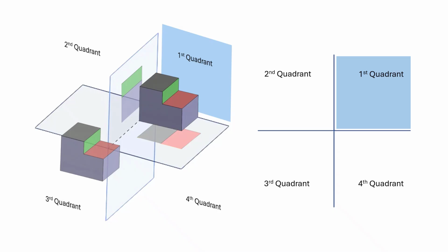Now, if we talk about third angle projection, the object is imagined to be placed in the third quadrant. This means the object is behind the vertical plane and below the horizontal plane. In simple terms, the projection planes are between the observer and the object. You are looking through the projection plane at the object. The plane acts as a transparent glass screen and you draw the view as you see it on the screen.